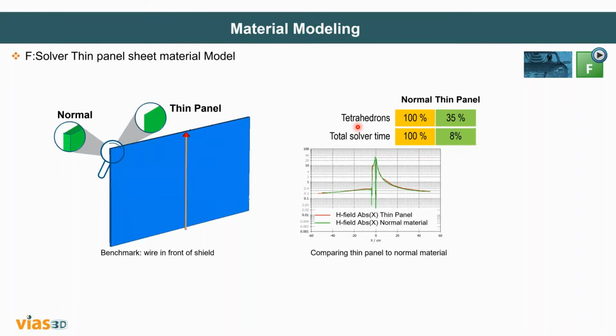So these are the same materials that the time domain solver has been consuming for several years. The thin panel materials have been defined as sheets. If you see a normal material with 5 layers, it has an equivalent model of a thin panel, which is now supported in the frequency domain solver as well.